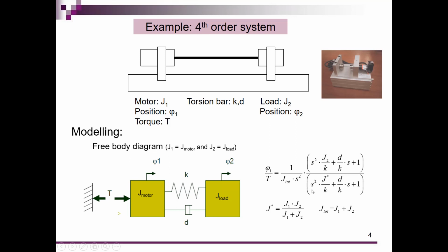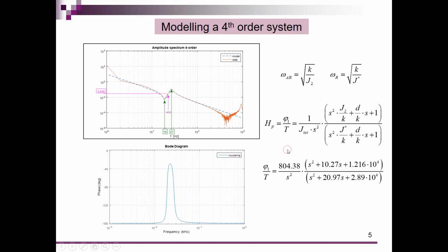When this is at the lowest, we have a peak in the frequency domain, which we call the resonance frequency. And when the numerator is at the lowest, we have a dip in the frequency characteristic, which we call the anti-resonance frequency. So let's make a Bode plot out of it, and I've done that over here.